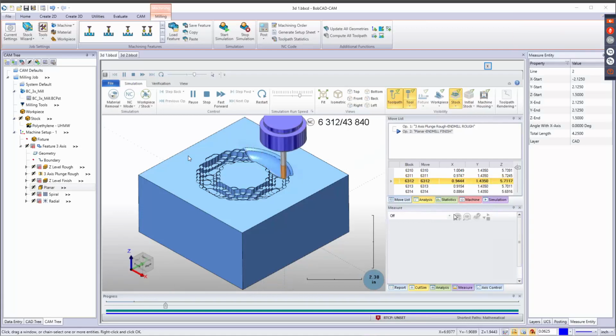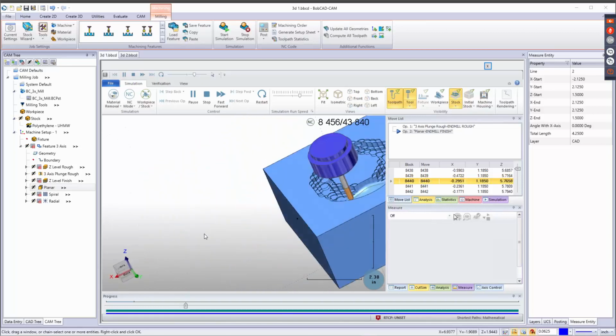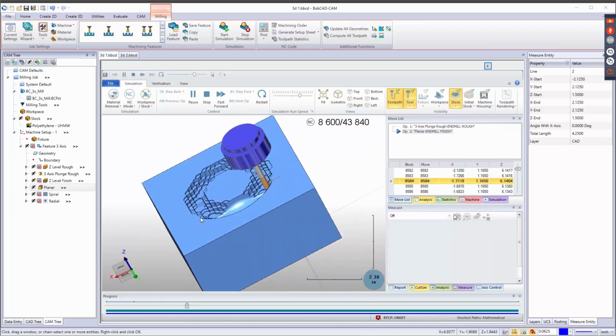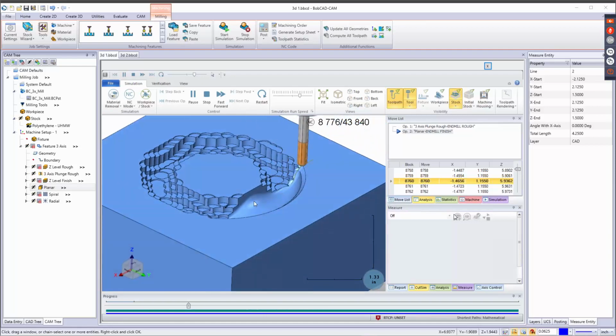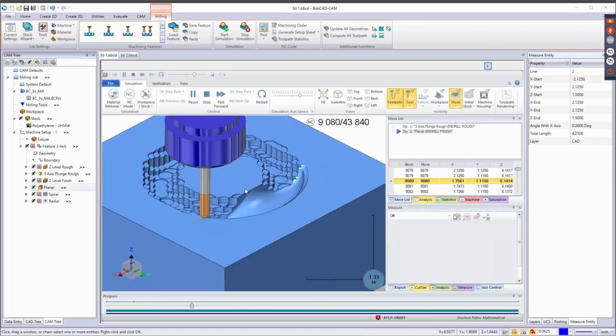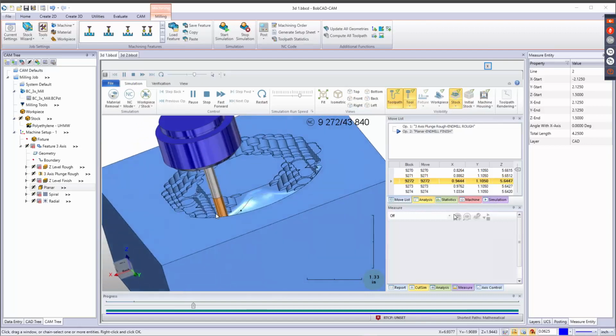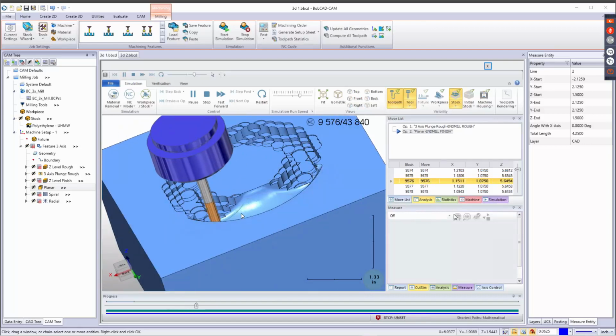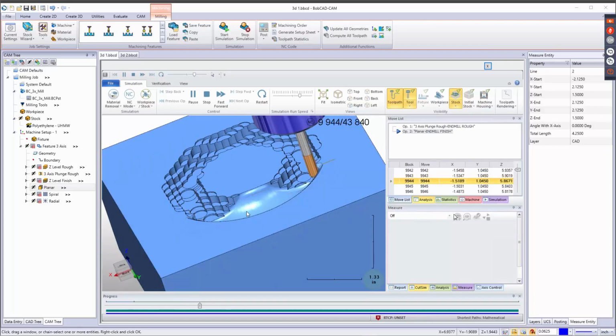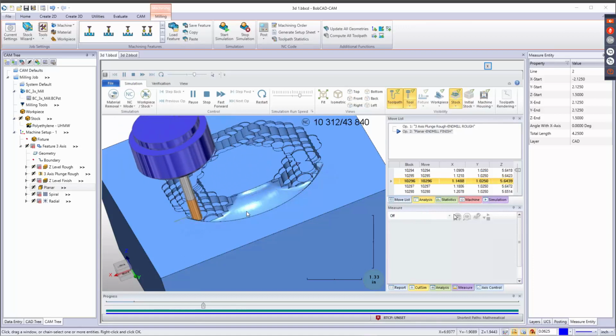After we're done looking at these all in simulation, I'm going to go over a few of the Pro toolpaths just to show you. I'm going to bring in an already known part. You can swing this around by holding your left mouse click down. It'll rotate for you so you can see that's a lot of material that's taken off. So I may end up doing something different in there, maybe a smaller tool, maybe a smaller step over and depth of cut or something like that.